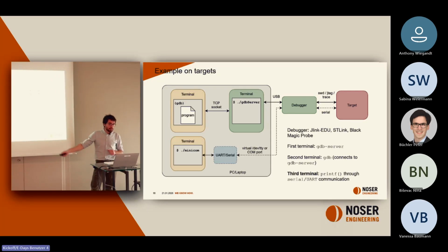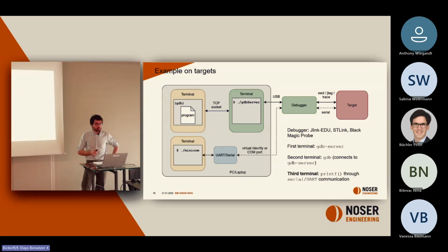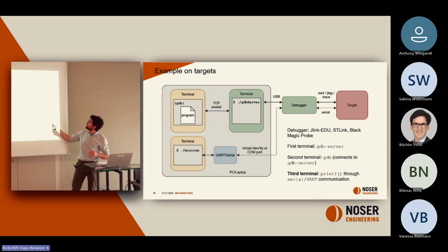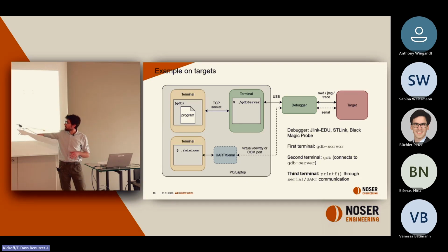And now there is one last thing I could show you, which is to put actually the serial communication also to read it. You don't need any GDB for something like that, but it's very useful. Some debuggers propose a virtual COM port. And actually, for example, ST-Link has, directly inside of it, serial communication on a default UART port, which means all the printf, all the log communication you want to have in your target, you can forward them directly to serial and read them with Minicom.